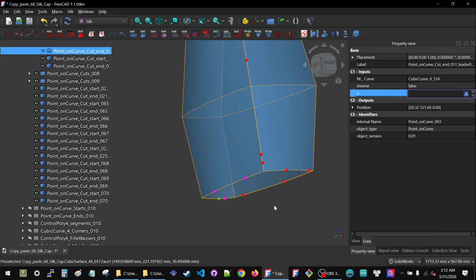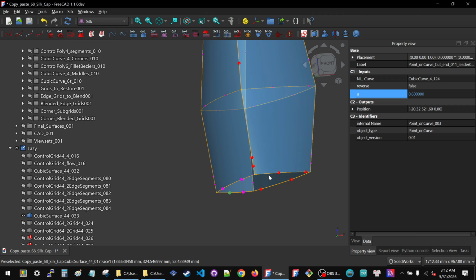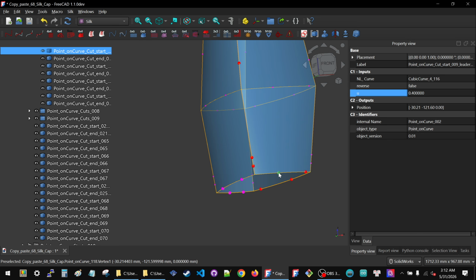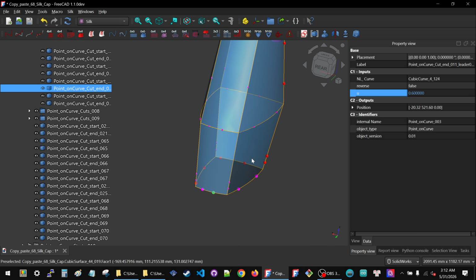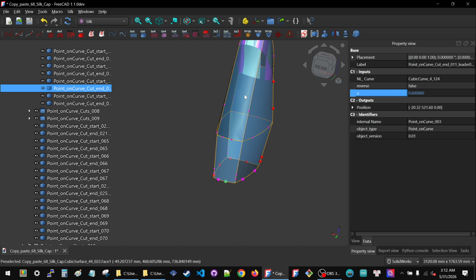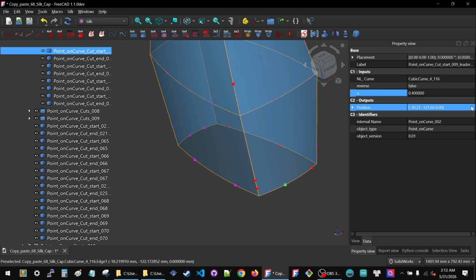Okay, F5. And that worked. This point here feeds its true spatial position to this one. So 0.4 on this one has become 0.6 on this one through the use of a formula. And because I did it this way, the points that were already following this one also follow correctly. Let's test that. This guy here, I'm now going to set it at 0.1. Hit F5.